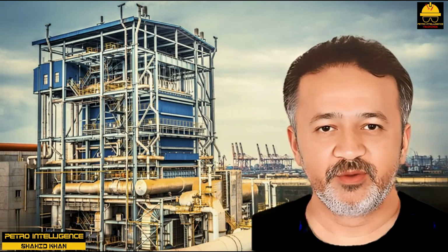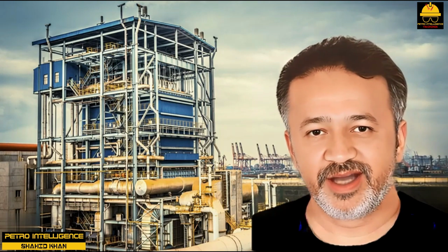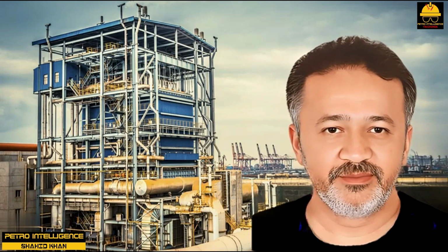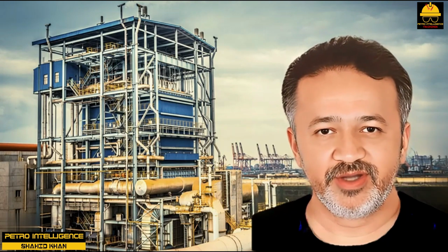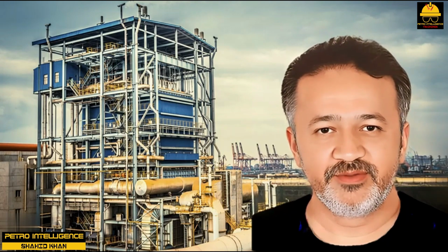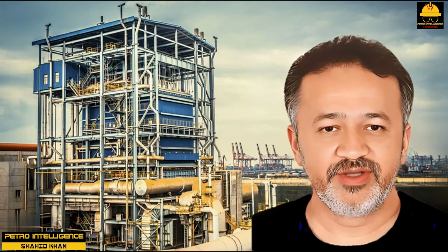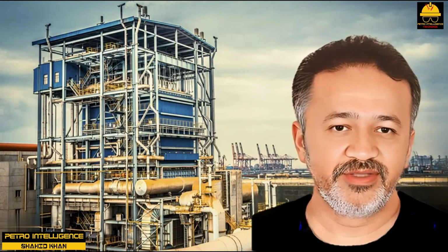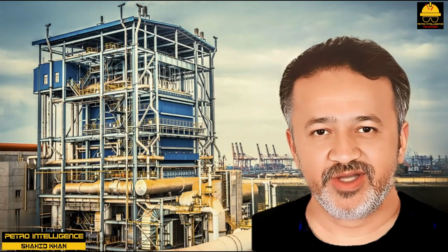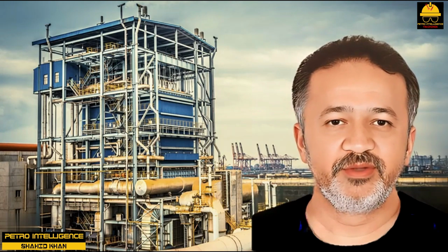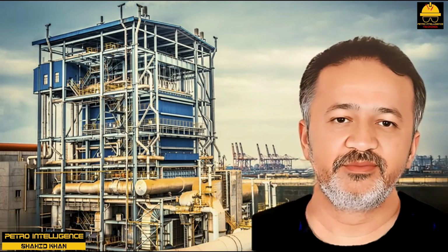Special techniques are required for tube side cleaning, but cleaning the tube side is not any more difficult than cleaning conventional tubes. At one refinery, on a 180,000 BSD crude unit, 2 parallel, 6,000 square feet, titanium twisted tube bundles have been in service for a number of years. Crude tower overhead vapors plus steam are condensing on the shell side. Crude is on the tube side. Fouling on both the shell side and the tube side appears to be quite minimal.